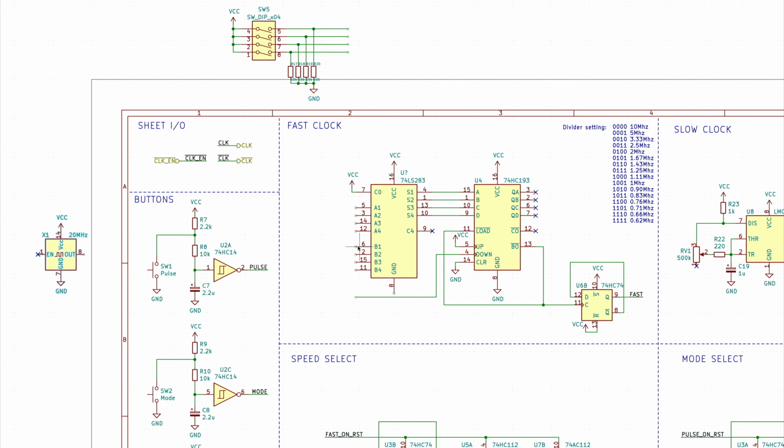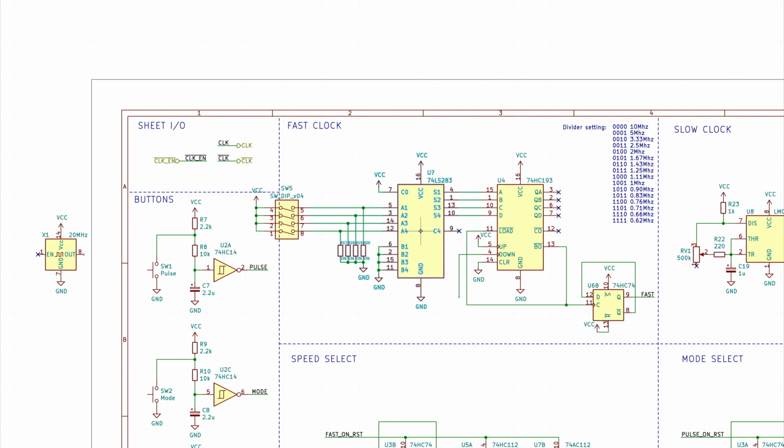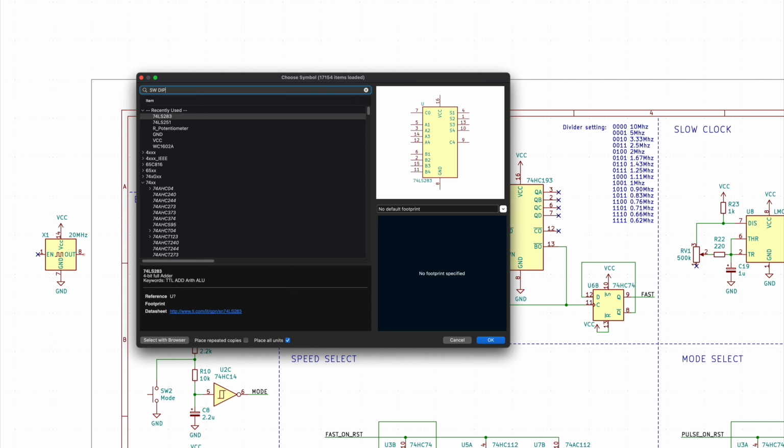And then I'll connect all of the second bits to 0, as well as the most significant bit of the first nibble. Remember, we want to ignore all the values where it is set. So we can remove this section here and switch to a 3-bit dip switch.